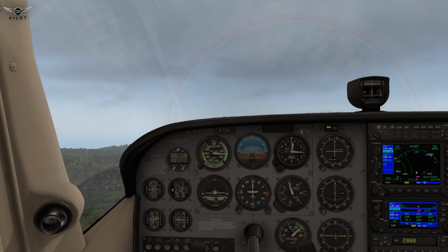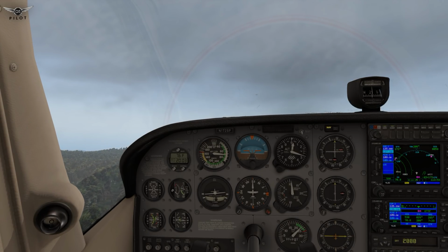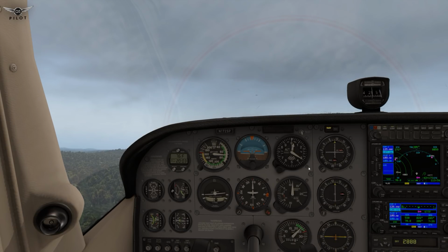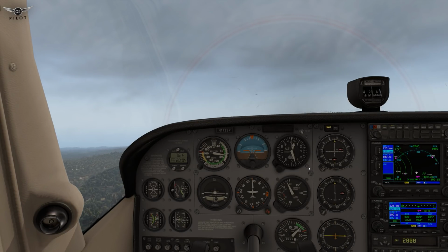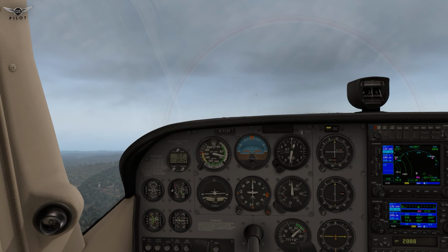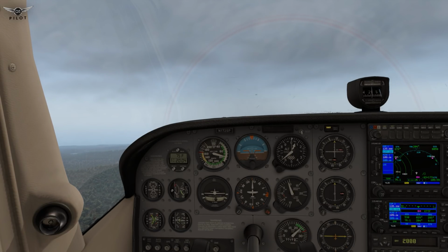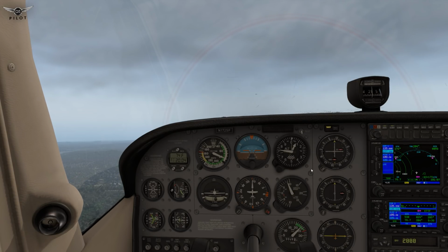Right, use right rudder to neutralize any yawing to the left. Our best angle of climb speed is 62 knots. Our best rate of climb speed is 74 knots. If we encounter heavy turbulence, we need to be at or below maneuvering speed, and remember this will decrease as we burn fuel. In this aircraft we normally turn with a 20-degree bank. And with a 20-degree bank, we want to begin our rollout from the turn about 20 degrees before reaching our desired heading.